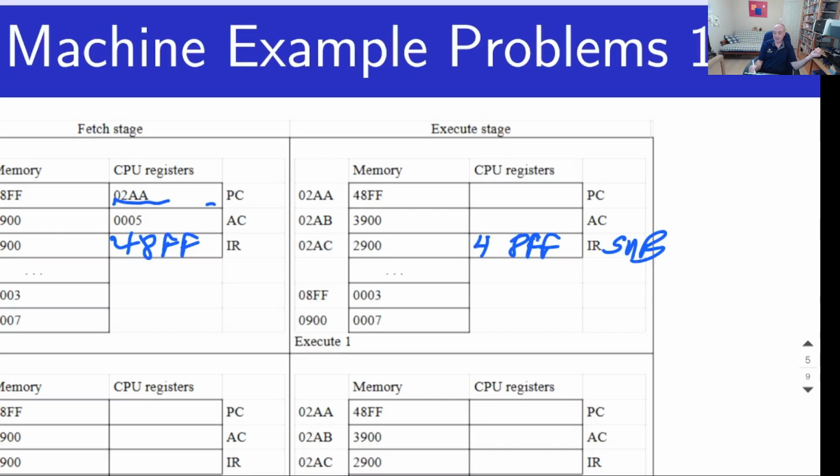And then the other 12 bits, the next 3 hexadecimal digits here, represent the memory address, which is one of the 2 operands for the subtract, right? For these problems, you should always have the accumulator as the first operand. So our accumulator has a value of hexadecimal 5, and be careful, you always need to be aware that these are hexadecimal values.